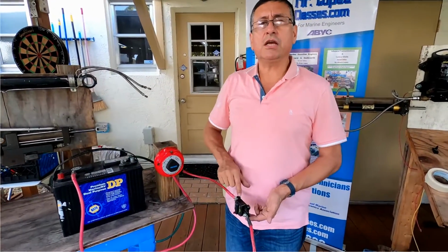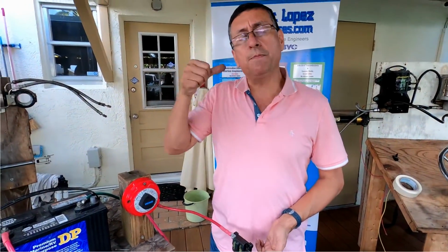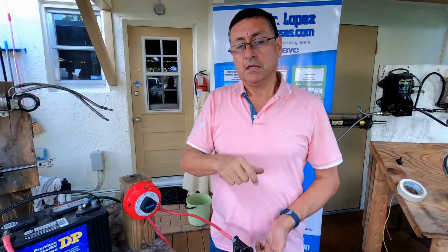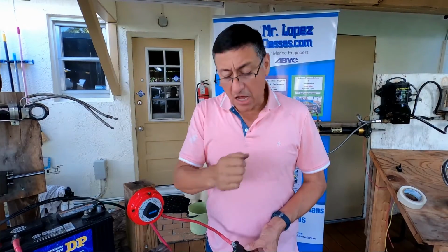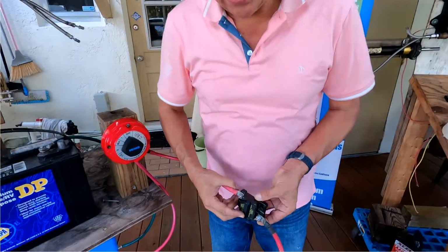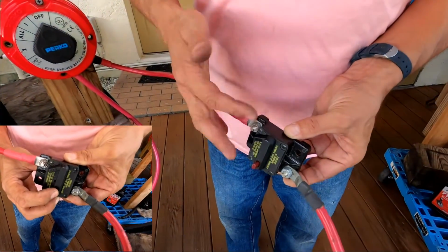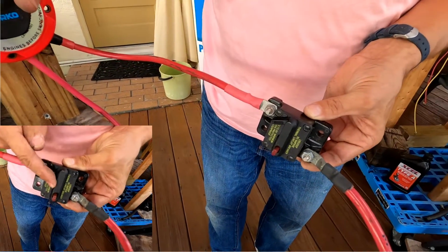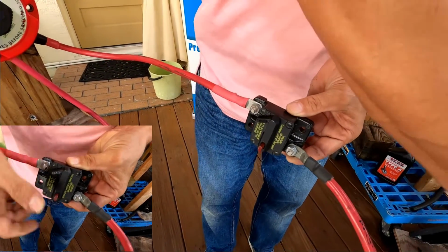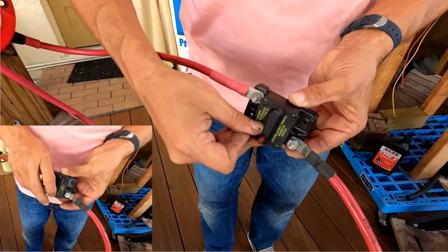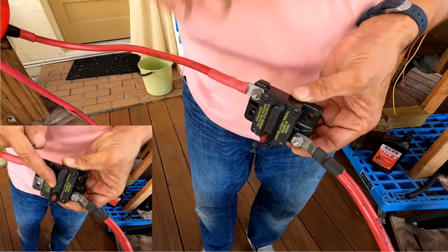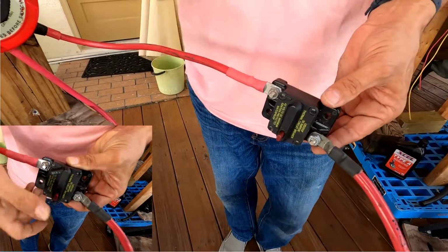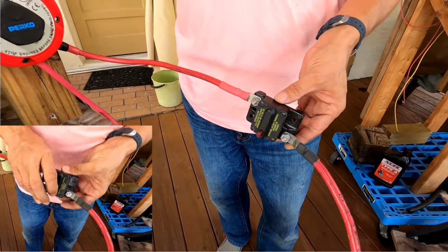The fuse is critical, and the emergency push button, both of them. At the moment the motor is locked, this element opens, the fuse opens, and protects the battery, the selector and the motor. This is the fuse, and the capacity is according to the capacity recommended by the manufacturer of the motor.